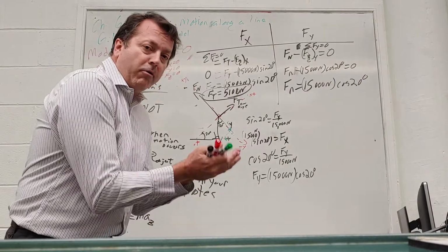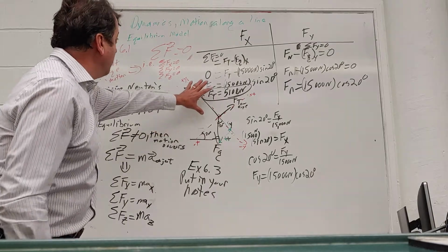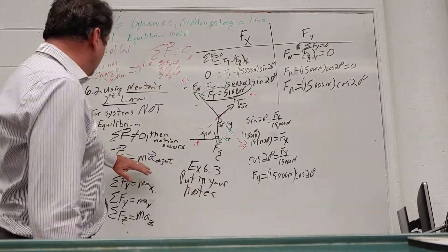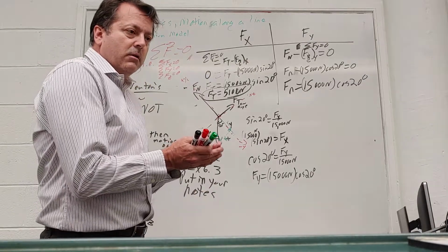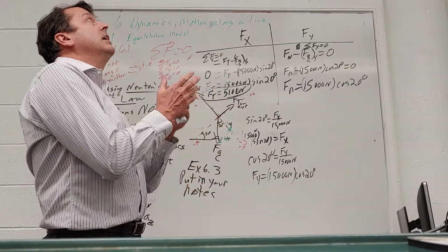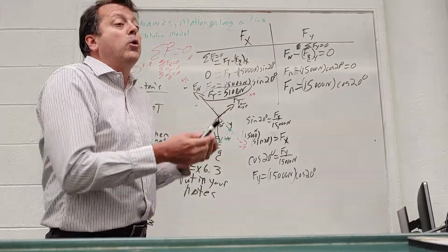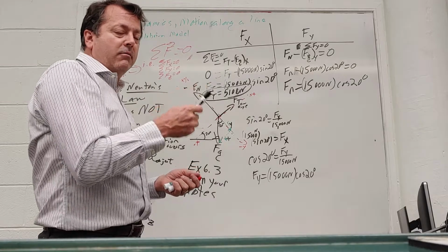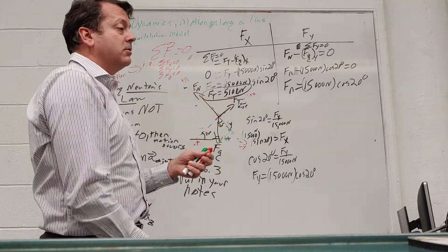Because the first part of the problem, the burn phase, if you think about it, is a dynamics problem. It's the sum of the forces. We've got to look at forces and how much they cause motion. That's Newton's second law. We've got to do this for the boost phase. But the coast phase is throwing something in the air with an initial velocity. The rocket just gives us a whole lot more initial velocity after the boost phase of that motor. Because now it's just coasting, just like that marker is.